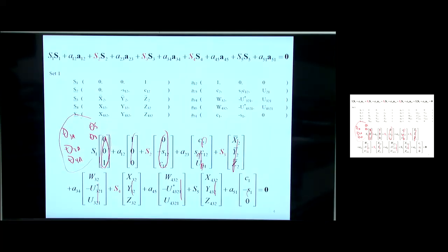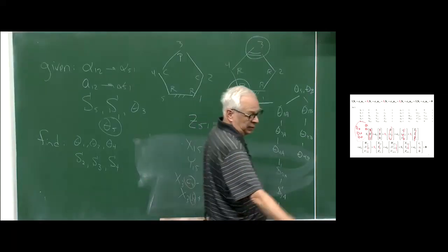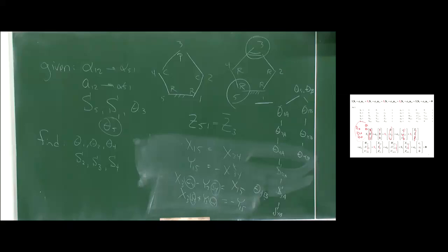So it's a lot of work to evaluate all those vectors. And I didn't have to pick the first coordinate system. I could have done it in any of the coordinate systems, and I would get the same answers for those three scalars, S2, S3, and S4. At this point, from the three equations and three unknowns, we can go to our solution tree and say, I got S2 for the A, S3 for the A, and S4 for the A. Then I'm going to go back to those same equations, and we are going to put the B case angles.